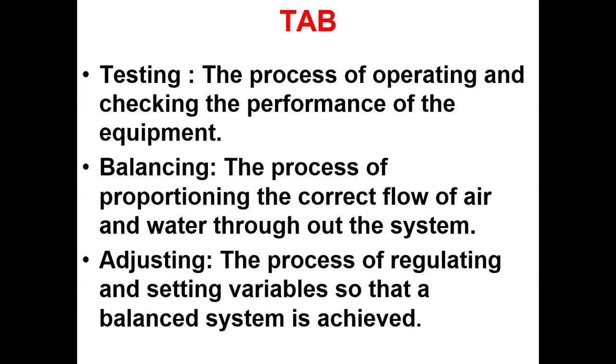Okay, so once you got the velocity according to the Q equal to AV method, for example, how do you check in a diffuser that 500 CFM is coming out of the diffuser itself? How do you know exactly that 500 CFM comes out? Very simple. Just place an anemometer right on the outlet side of the diffuser, which means the opening of the diffuser. So, you will be getting a certain value.